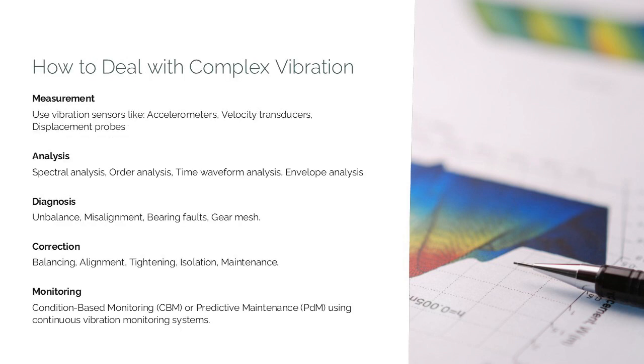How to deal with complex vibration. Dealing with complex vibration involves several steps. Number 1, measurement. Use vibration sensors like accelerometers, velocity transducers, displacement probes. These sensors collect time domain data which can be transformed into frequency domain data using fast Fourier transform, FFT.